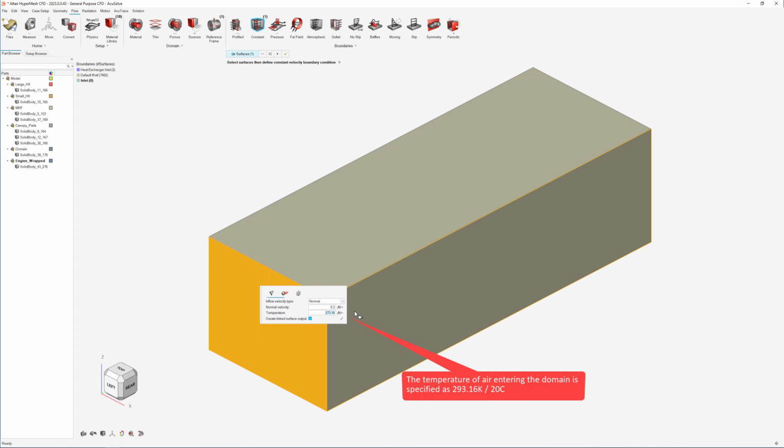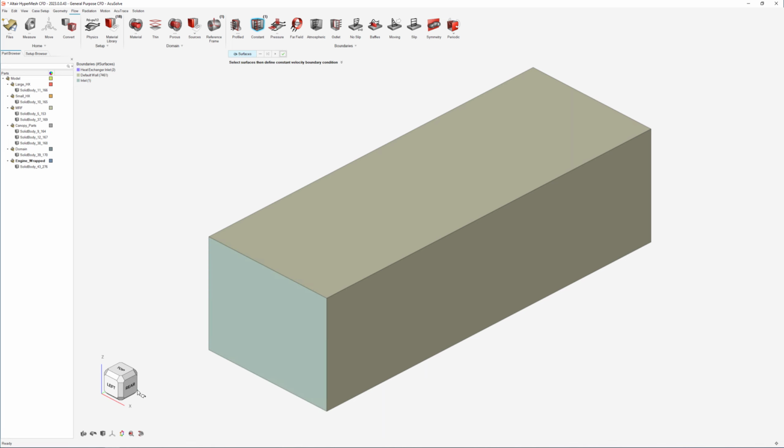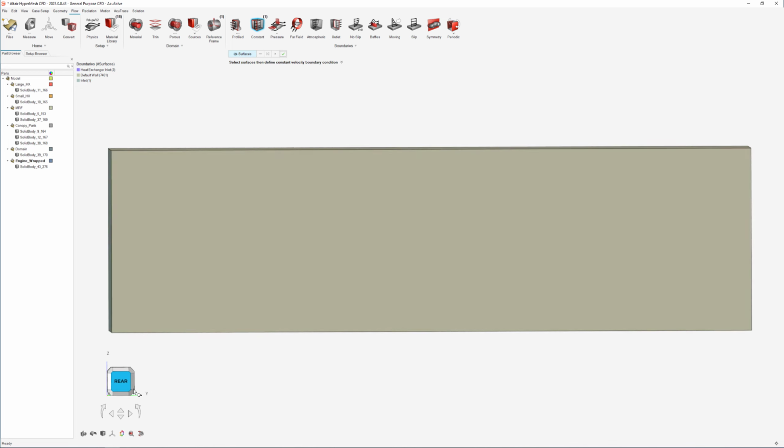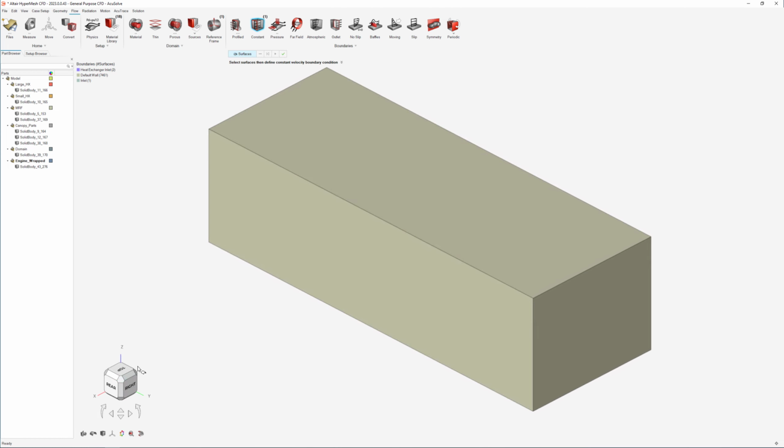In reality, the creation of the flow field is exclusively due to the rotation of the fan, with the ambient air around the geometry being static. However, this would create large swirls within the domain and consequently reverse the flow on the inlet and outlet faces, causing instability in the simulation. For this reason, we define a small inlet velocity to impart a predominant direction to the flow, avoiding the flow reversal while minimizing the disruption of the flow phenomena near the canopy.